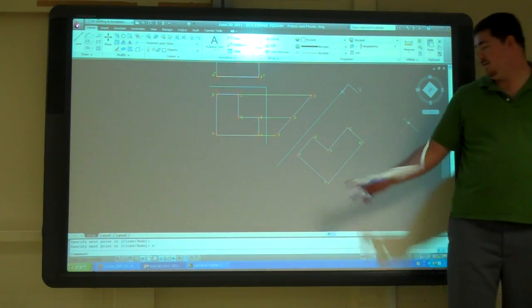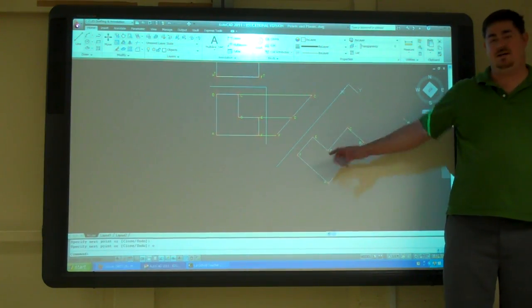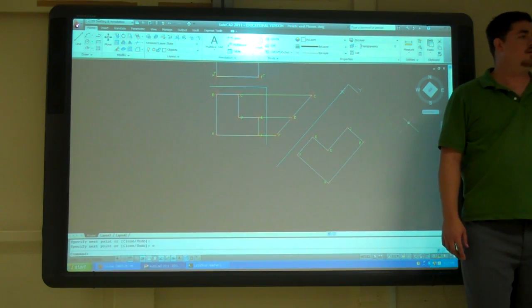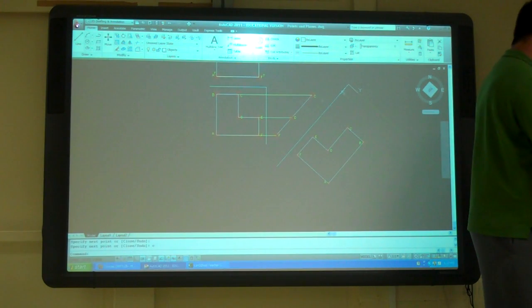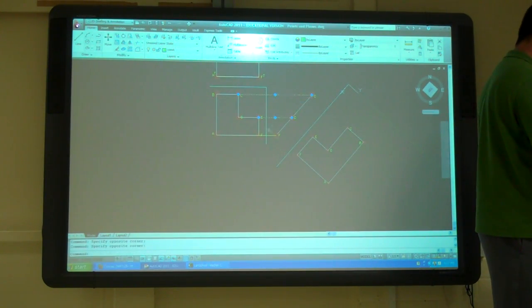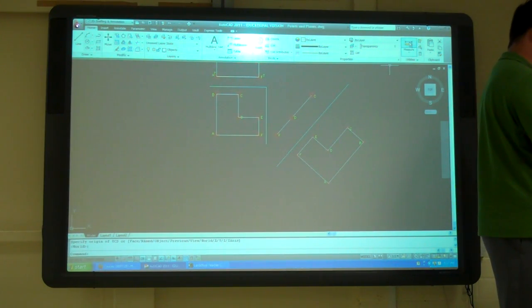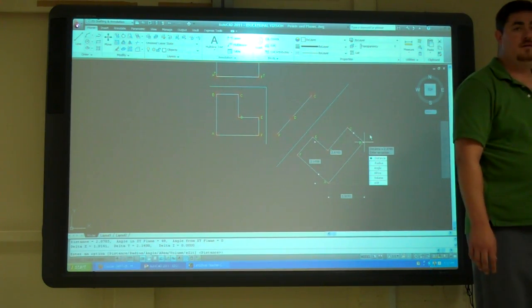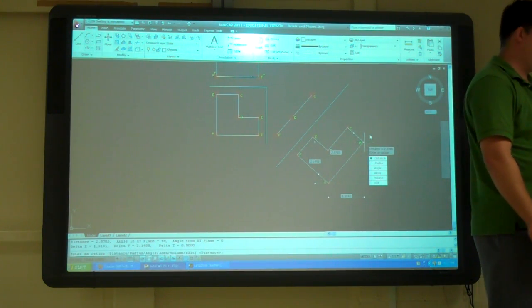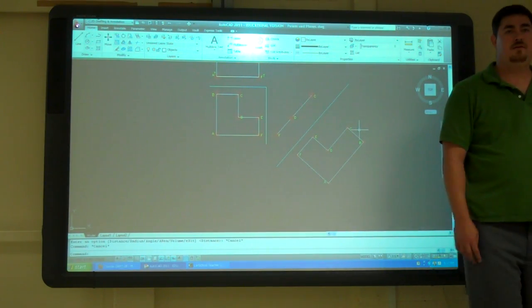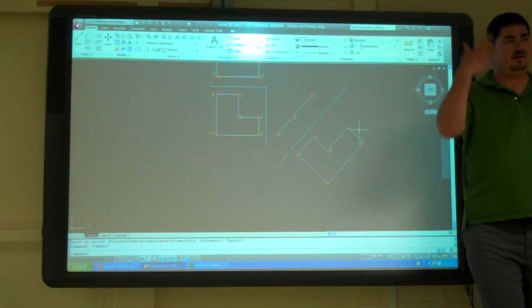Right? Now this view is true length, true size, and I can actually measure those distances and see how big that plane is. So UCS, enter. And so I can go in and use measure and measure it out and see it. What's another way I can see the length of that line? And then maybe I can leave it on the screen.